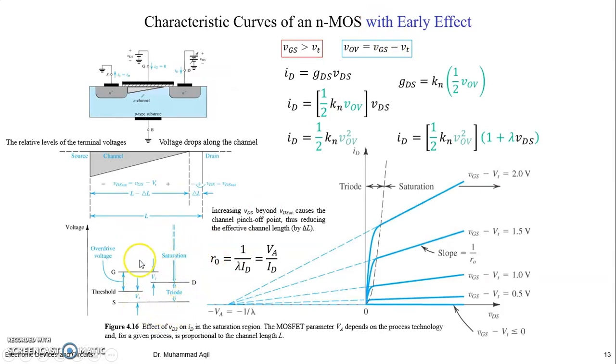this one. We have explained you all these things, right? If you want to revise it, please rewind this video and then see what we have said about this. Actually, we have applied the gate voltage more than the source voltage. How much more than? At least greater than VT. And how much VGS is greater than VT is your overdrive voltage VOV. And if this is happening, it means you are having a channel and you are having a conduction, depending on how much VGS you have, right?